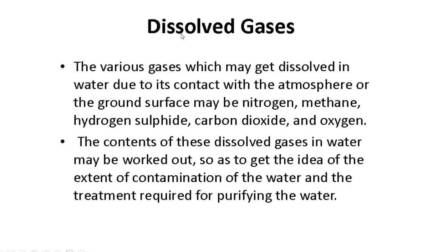Then we have dissolved gases. The various gases which may get dissolved in water due to contact with the atmosphere or the ground surface may be nitrogen, methane (CH4), hydrogen sulfide (H2S), carbon dioxide (CO2), and oxygen (O2). The contents of these dissolved gases in water may be worked out so as to get an idea of the extent of contamination of the water and the treatment required for purifying the water.